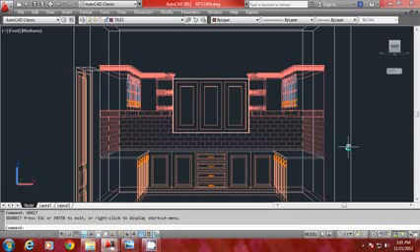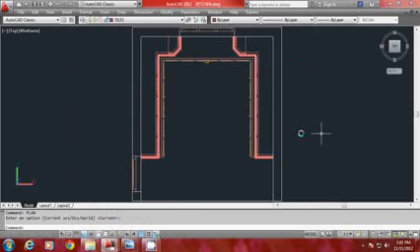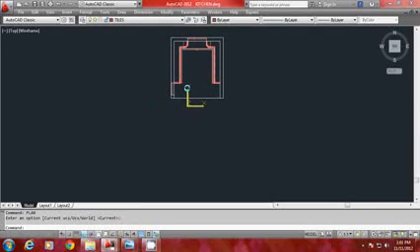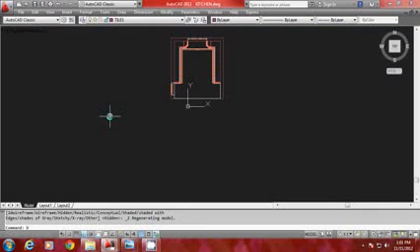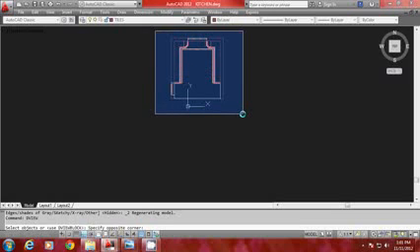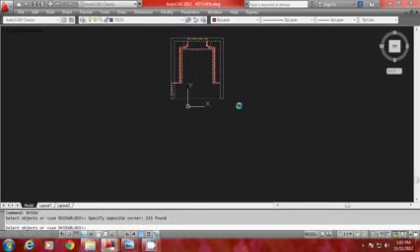So here we can't control certain parameters like the position of the camera, the focal length of the camera, and the type of perspective, etc. So this is where we have to make use of a very useful and versatile command in AutoCAD, and this command is called dynamic viewing or DVIEW. So just go to the DVIEW command. You have to give the DVIEW command in AutoCAD. So I'll give DVIEW and it'll ask you to select the objects. So you can go for selective visualization. You need to select only those objects which are to be visualized.